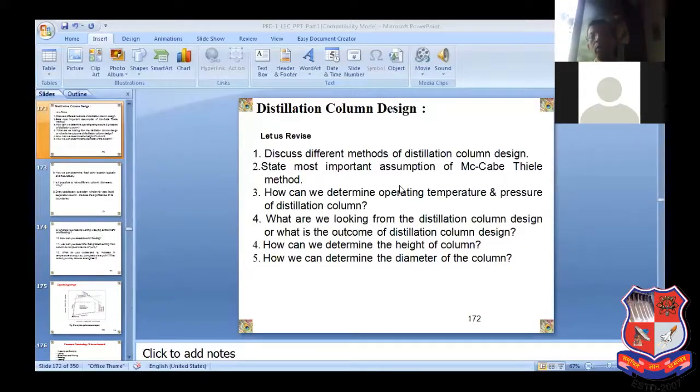Similarly, if you want to have a separation of components which remain in a vapor phase at atmospheric condition, in that situation you simply recommend to increase the pressure of the column and thereby increase the boiling point, so that you can choose its range which is feasible and economically viable. Fine. Second case, when you recommend the vacuum.